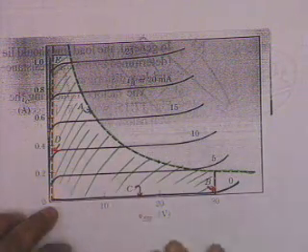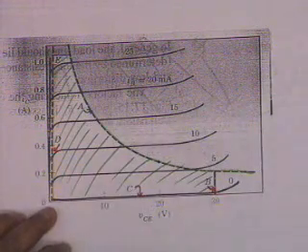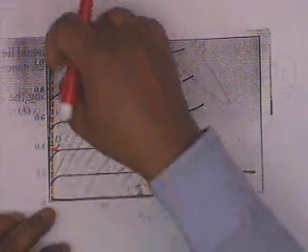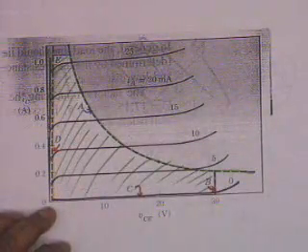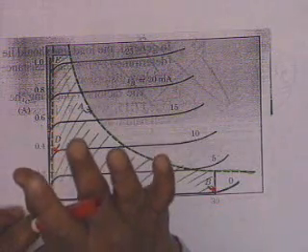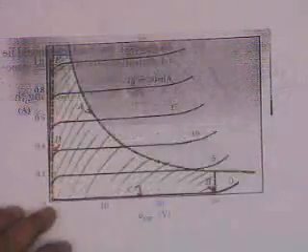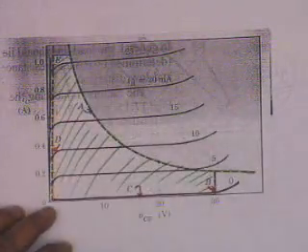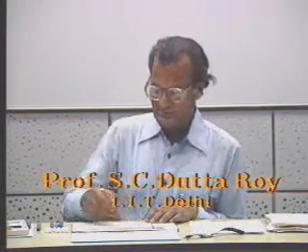You cannot increase voltage beyond 30 because avalanche multiplication takes place. You can increase the current beyond this, however, but the manufacturers, very clever people, say we will specify the transistor that you are going to buy from us only within a certain maximum collector current, and this sets the maximum. This sets the line E as indicated here.